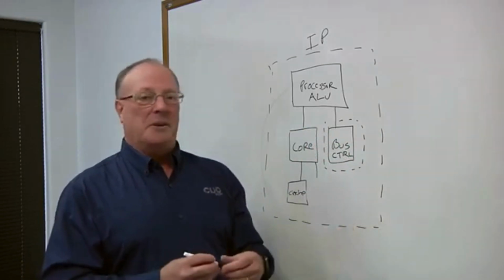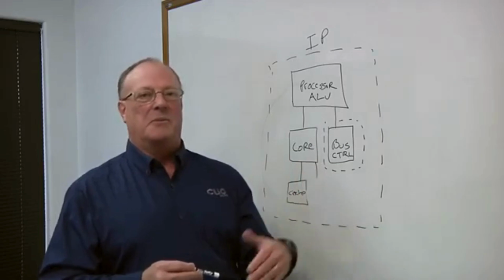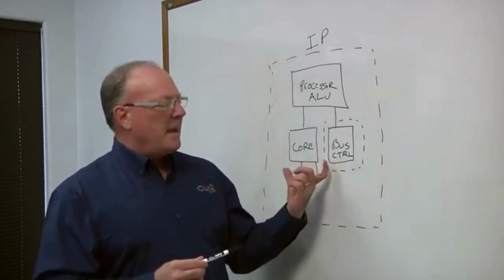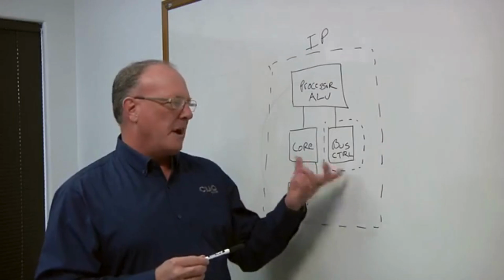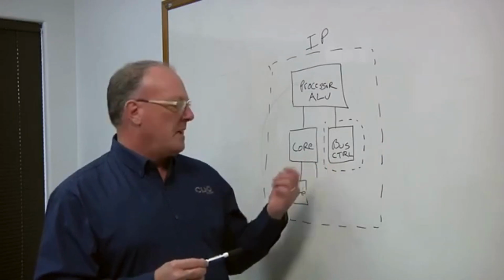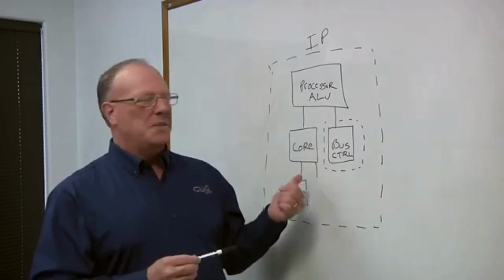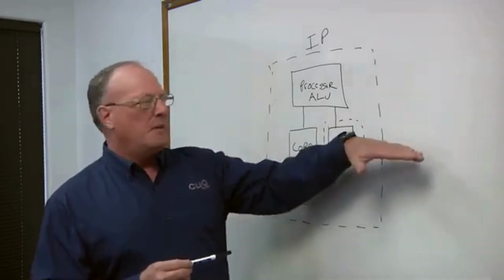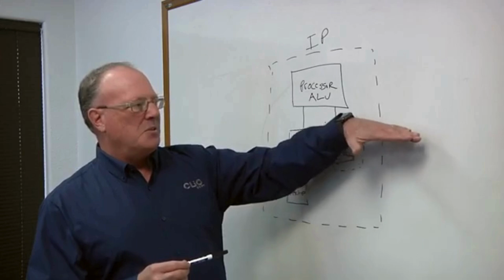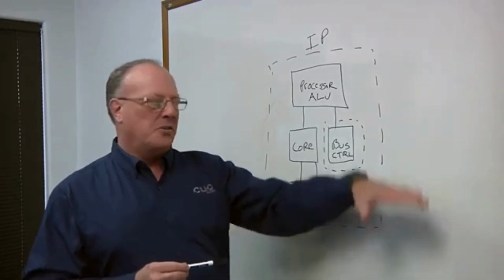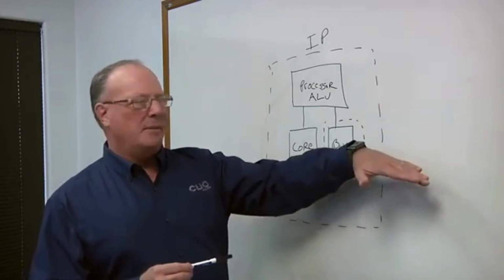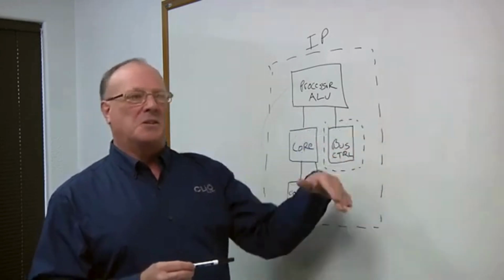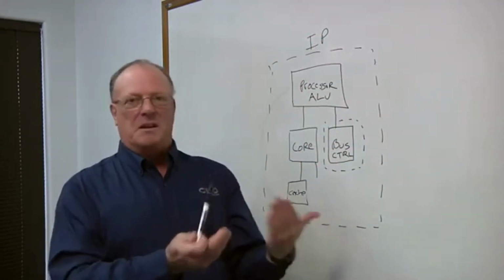So that's a problem. You don't want to actually make silicon with that kind of issue. And then there's also things like you may actually have different assets that come from Synopsys or Cadence, whoever the IP provider is, that depending on the options that you choose, you may need different assets, and it's good to account for all that. So VKIP tagging really allows you to snapshot everything that's in your design at the mask shop, and you can have people like TSMC or Samsung or whoever your foundry is, they can run a report and send it to you and say, here's what we think it contains, and you can make sure that it does.